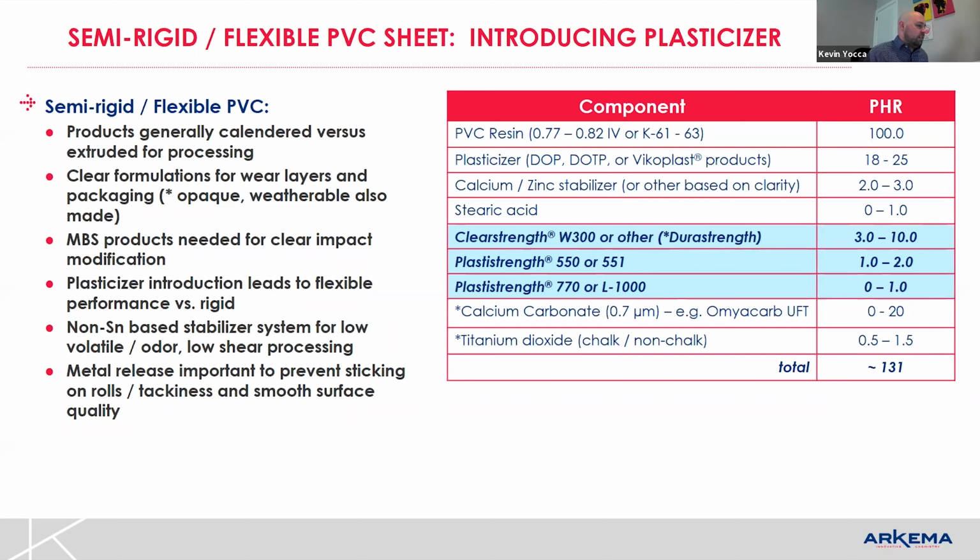So it's really just coming down to your consistency and comfort level, and then also what translates to your production. So I just encourage everybody to take a look at what it is per 100 cc and do that bulk density test, and keep track of it and see where the shifts occur. If you always use a set weight to do your Brabender work and it's consistent on the bulk density, you're fine. If you always use 100 cc's, it's fine.